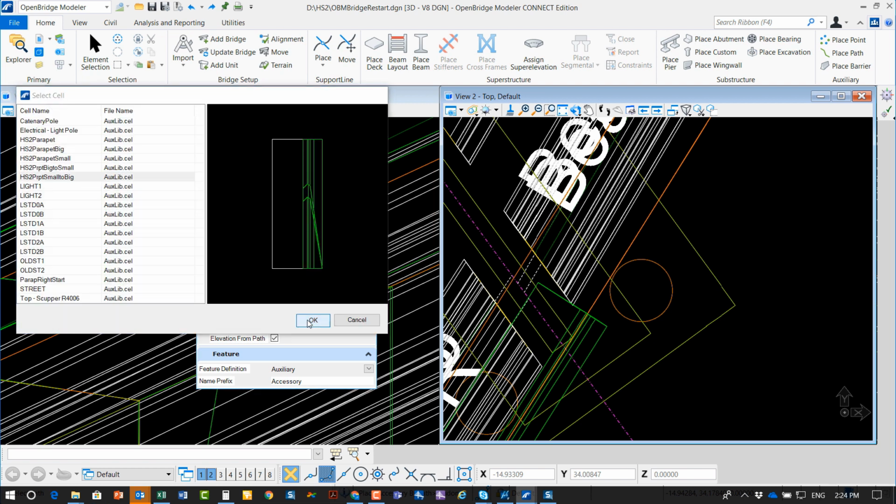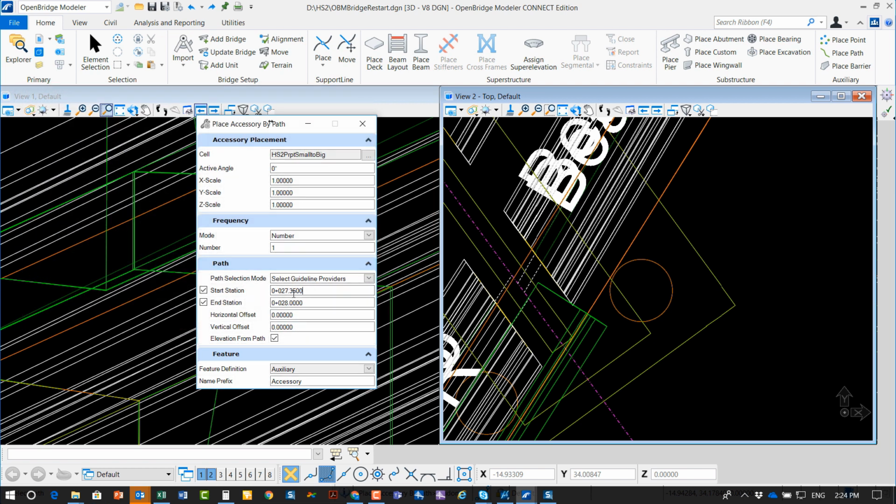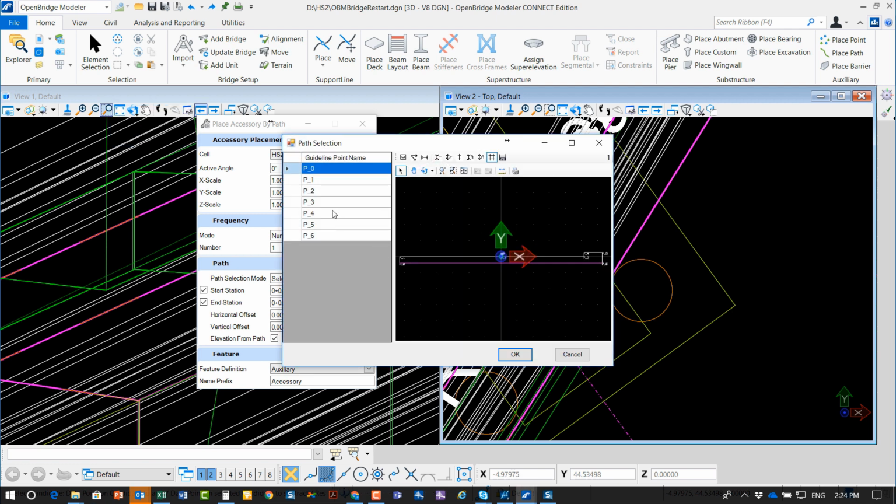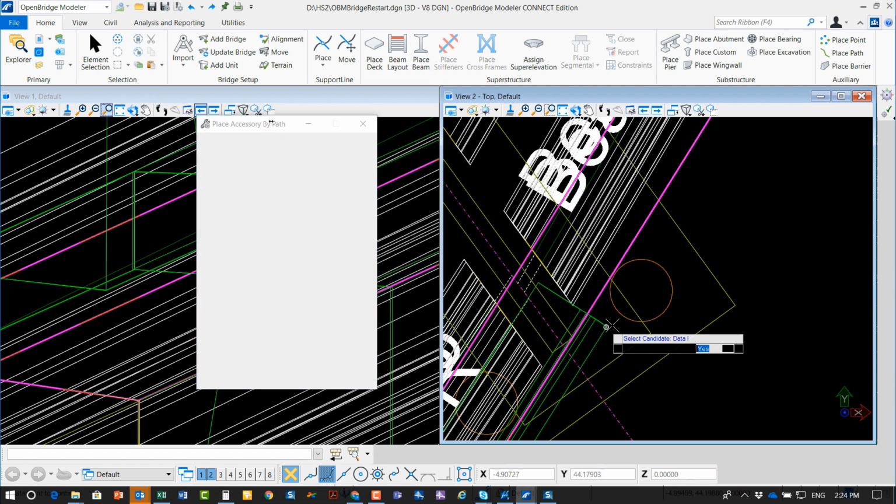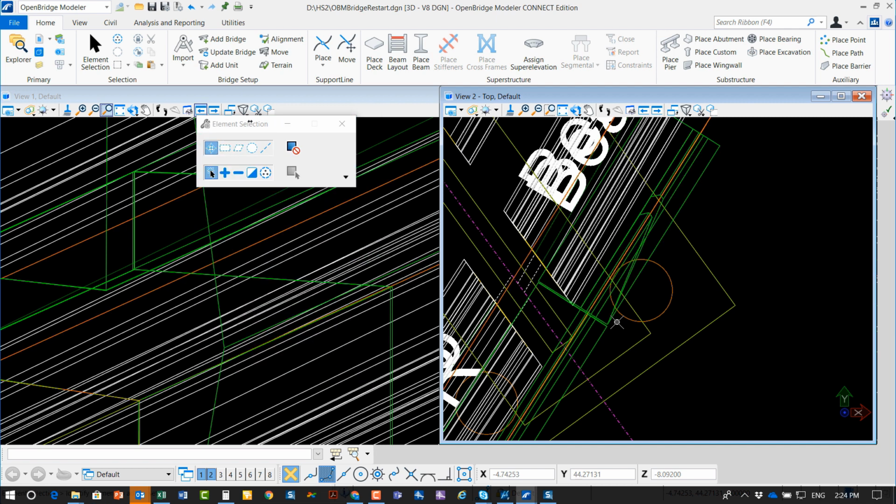So for example, when I have a transition between a small parapet and a big parapet, I just place them one by one. Otherwise, when I have several placed at 3 meters from each other, I can place them like that, and continue directly where I want to place them on each side.